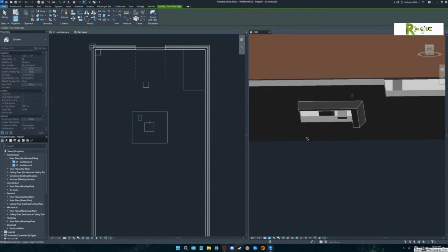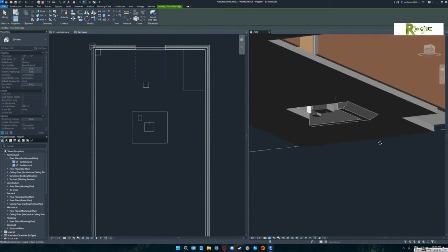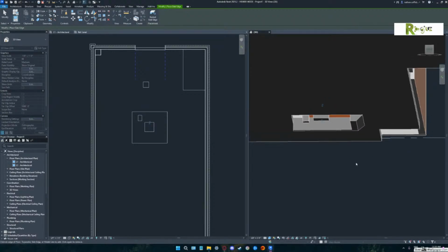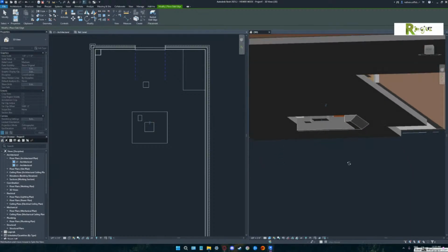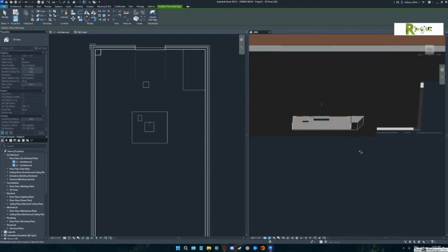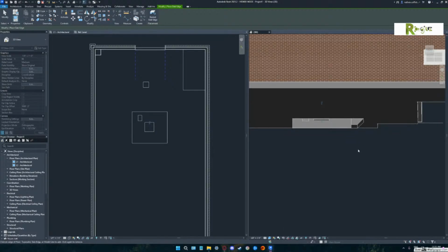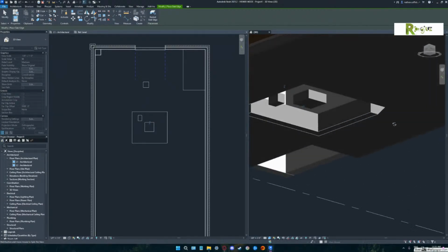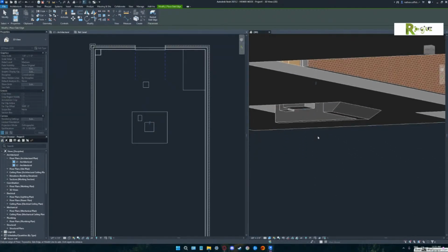No. Typically, when we pour a slab, we thicken it so that there's some strength so the concrete doesn't break. Does that make sense? Basically, what that's doing is thickening the floor up at the edge where it's going to sit on the footings or on the foundation wall or whatever, so that it just has more strength. Okay, so right here at this point. Yeah. Just gives more support. I got you. And we'll get into that more when we're going over construction processes.